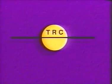The letter identification for an instrument symbol is usually arranged in this order. A circle indicates the instrument. The letter of the variable being controlled appears to the left. If the instrument records or indicates, this is indicated by a middle letter. The letter on the right side tells you the instrument that does the job.